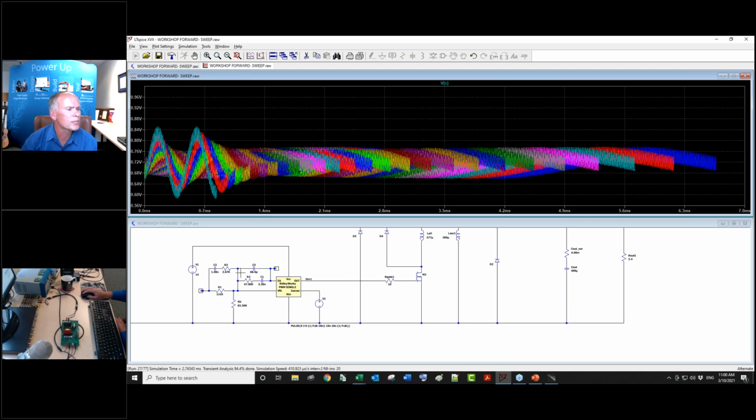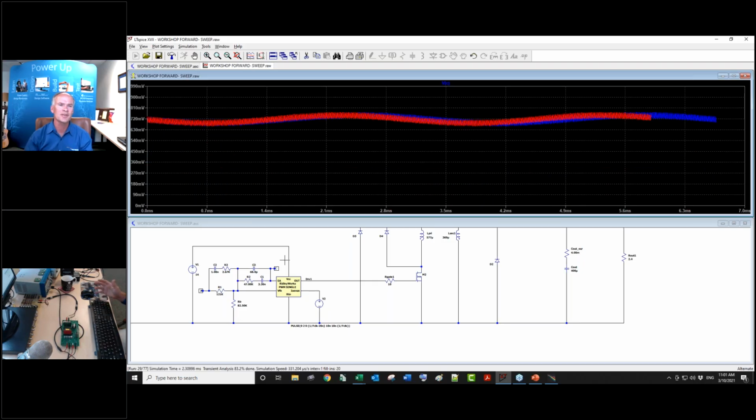Right, you can use the transient response again to tell you, are you absolutely stable? Do you have better than, let's say, 45 degrees? Absolutely, but if you don't have it, you can't see what to do to change it. There's just no information there.